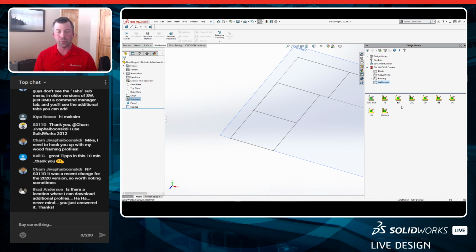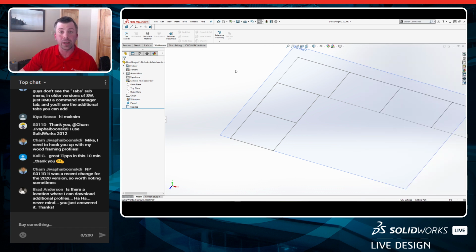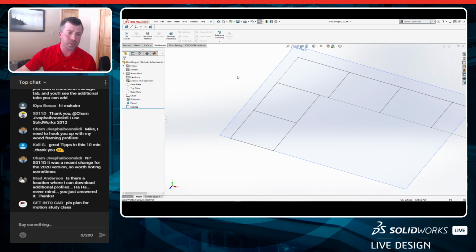All of those sizes is 1.5 by 1.5 by 1 3/4, whatever. They're smaller. So you need to be aware of that when you're going into a design like this. If I were to sketch it up and do 2x4 of everything and actually build it, it's not going to come together. So doing that and having the profiles, you can find softwoods configurations right on 3D Content Central.